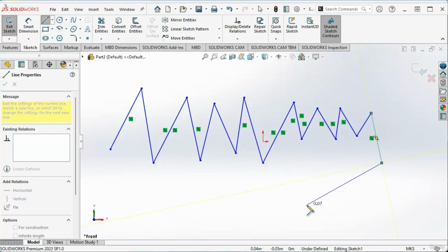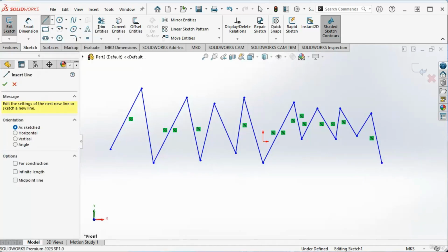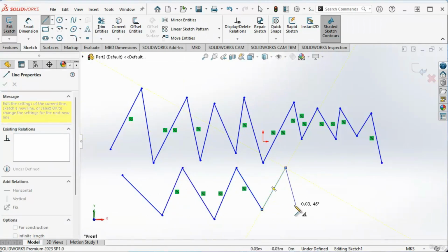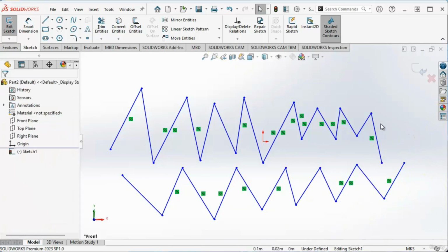Let us press the escape key on the keyboard. I'll press the escape key and you can see the line has disconnected. And we have created the first drawing. It's a set of lines. Let us do it again. Click on line tool. Click somewhere, maybe here. And I'll click here, here, here. Just go on creating points and it will generate lines. Press the escape key to exit from the command and to disconnect the chain of lines. So this is how you can create lines.